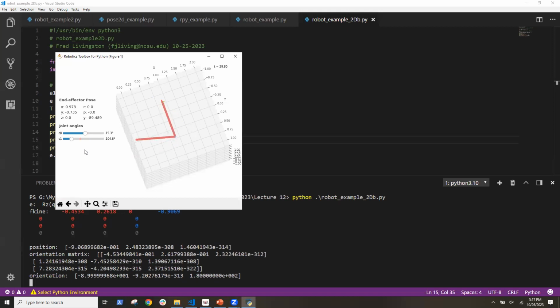Will have to add another degree of freedom, and so I'm just going from a 2-degree of freedom to an n number degree of freedom, and you can have redundancy degrees, so you can have a 60 degree of freedom, but then it's going to be kind of hard to build the machine. It's going to also drive up costs. So usually 6 is the good number because you hit all the degrees of freedom.